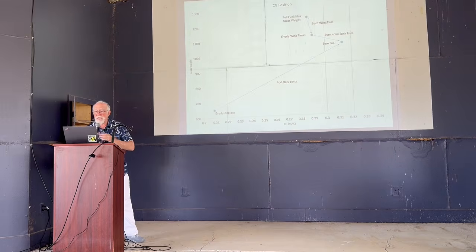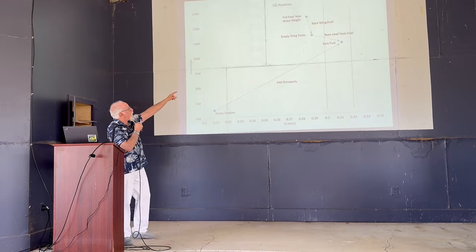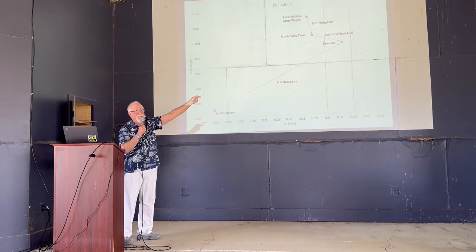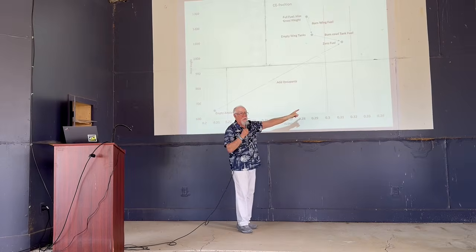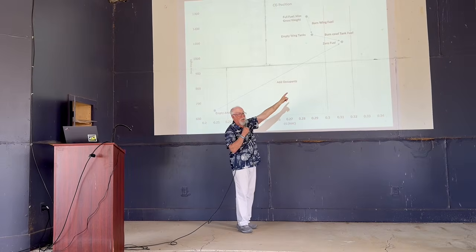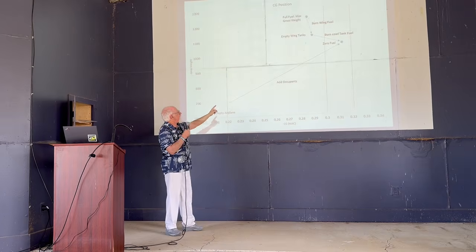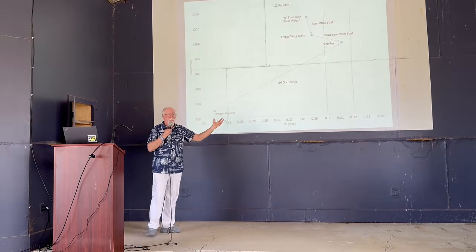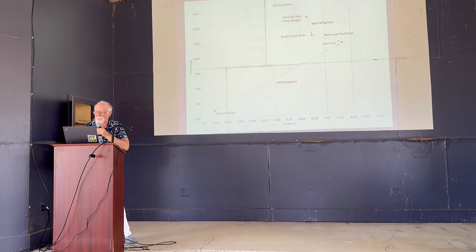So here's the situation that I talked about with the cowl tank. I take off at the top there at full fuel, max gross weight. I burn the wing tanks down, the CG's moving aft. I burn the cowl tank, and if my aft limit is at 30%, where it was with my original small tail, I'm unstable. And, you know, if I had less occupant weight, this would all move forward. So the solution at the time was to make the tail bigger. So now the aft limit's at 32%, and you're fine.